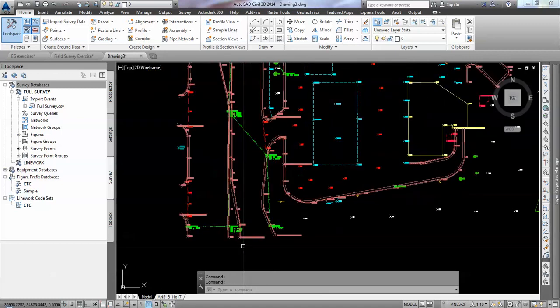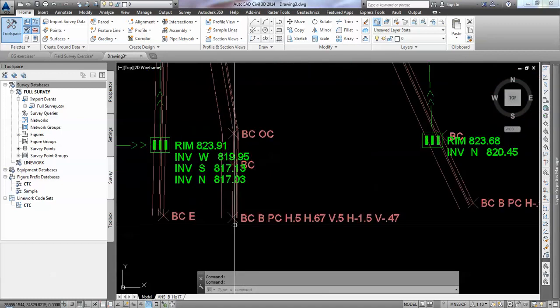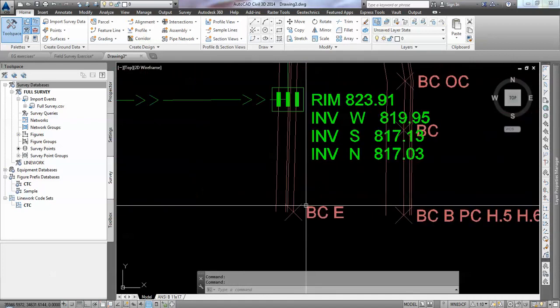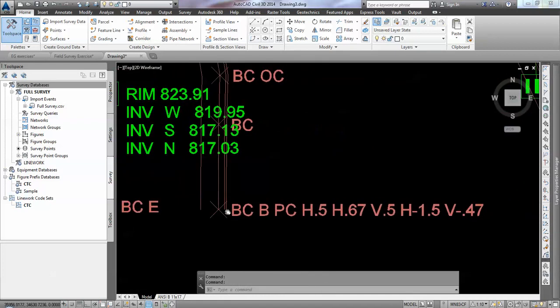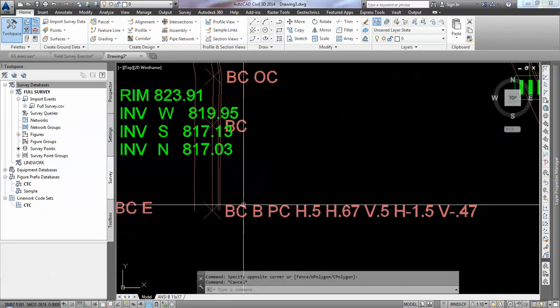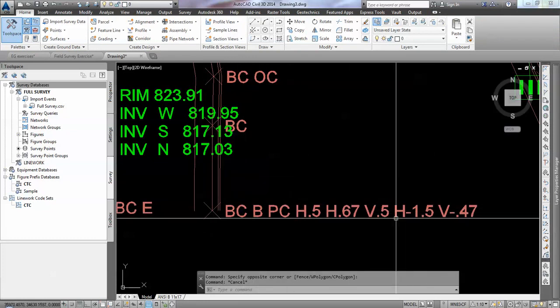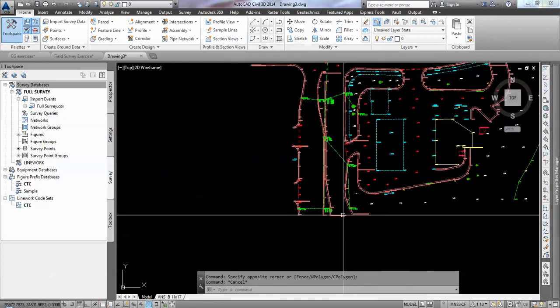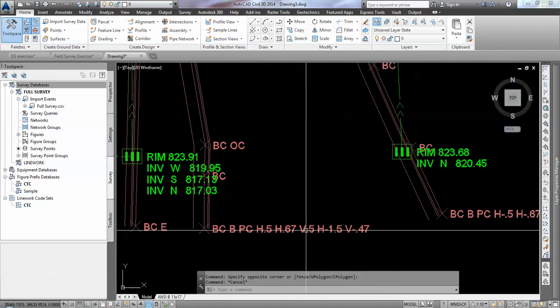Let's start right down here. Okay, I've got a median in the middle of my road here. I'm shooting back a curb. But this line, for example, is on the wrong side. Okay, so I should analyze my survey codes here and see what the problem is. And by the way, when you import your survey, the first thing you should do is look for survey point mistakes.